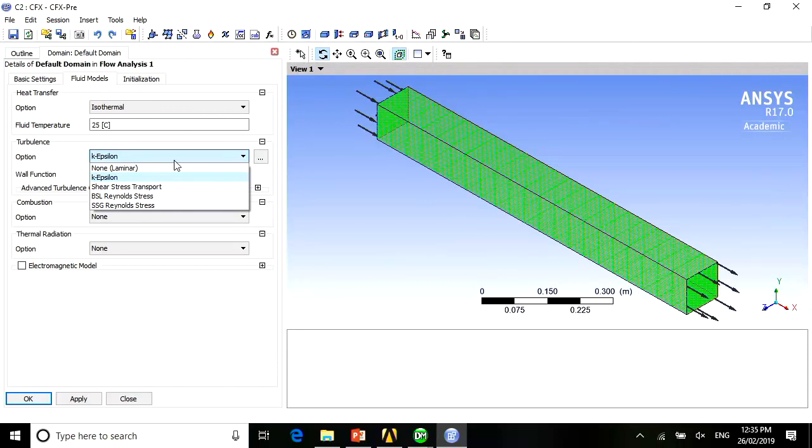When you have a model, you need to validate. You've got to make sure that the model works for your problem, or else you have to explore other models to see their performance against your specific fluid problem. So when you go outside to do a consultancy project, don't think that K epsilon can solve everything. You have to do trial and error to see which model is the best.